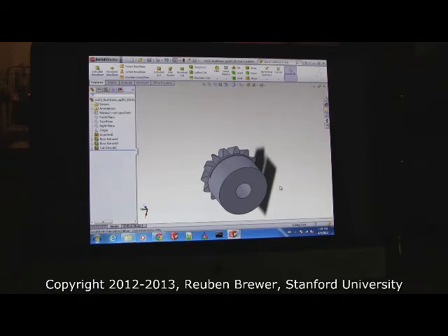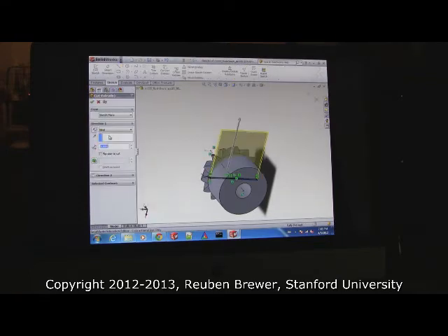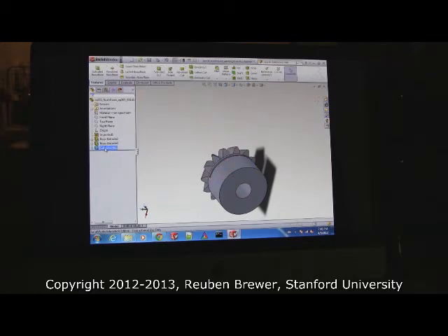What was the last step you did for the cut? I have the rectangle. Okay, does it look like this? No, no yellow. Okay, do you have a sketch down here? Yeah. Okay, hit the sketch. Select that. Now look at my screen. Press this button. Now does it look like it's going to cut? Yeah, set it to 1 inch. Yep, set to 1 inch.